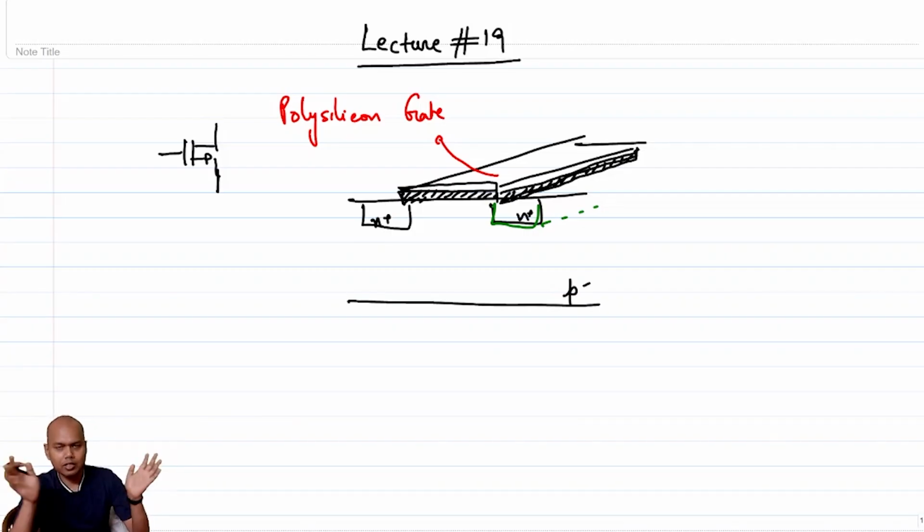So if you have a million transistors, we first probably will perform the operations on etching your wells wherever necessary. Then we will be performing operations of doping for all the transistors wherever necessary, and so on. Similarly, when you want to connect multiple nodes of the transistors or passives, we'll be digging holes and depositing metals in such a way that all the transistors in the network are connected as we essentially want.